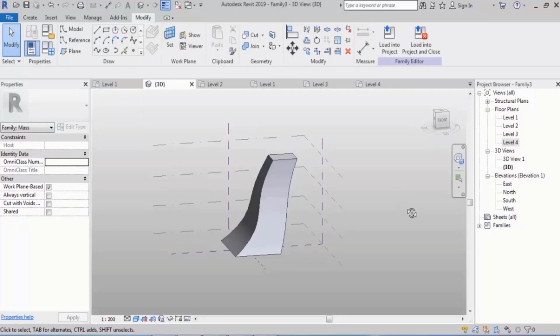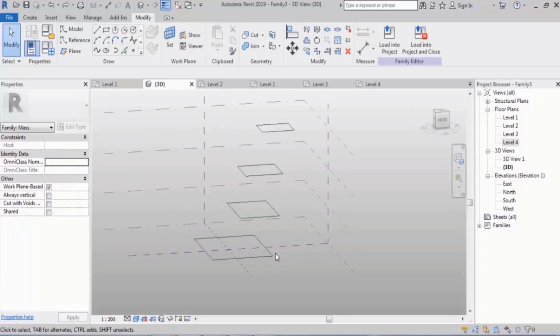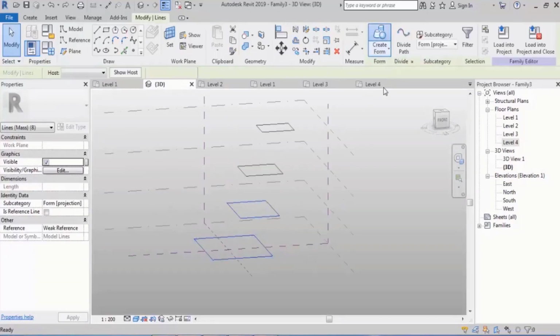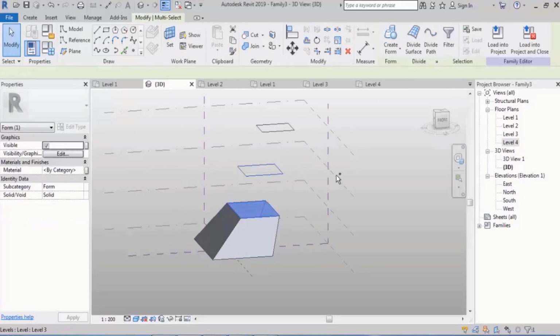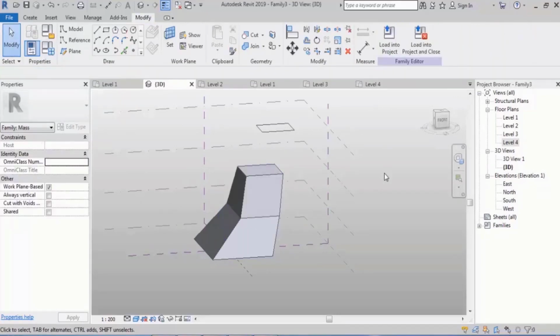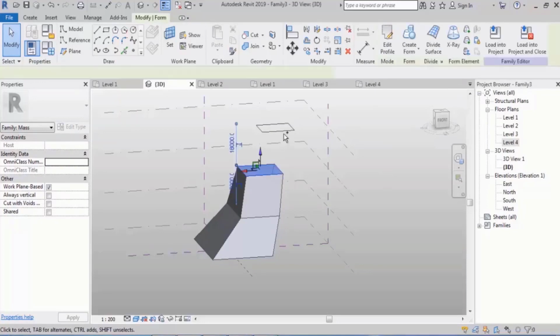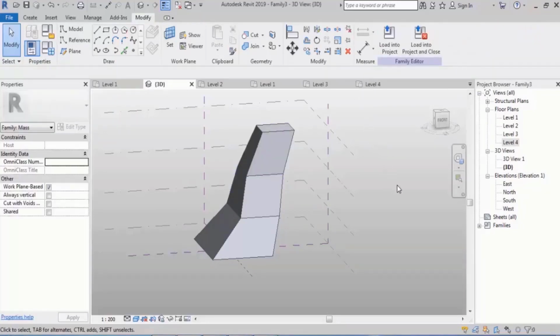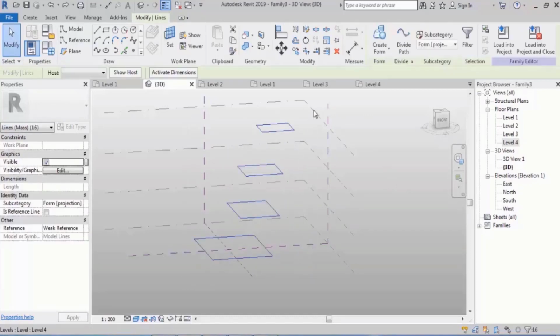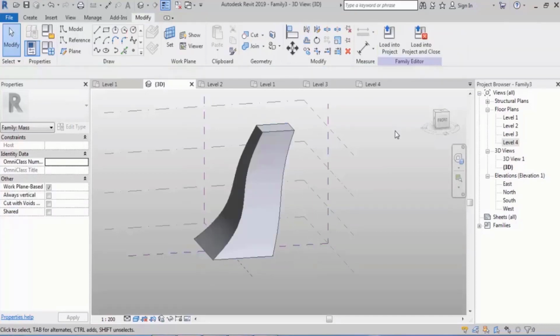In Revit, forms are connected to each other only curvedly, right? If there are two, yes, the form will be straight. But if there are more than two, they will be curved. But one of you might say that, no, I want them to be straight. Well, it will be difficult because you have to connect them 2 by 2. As you see, it's straight as long as there are 2 of them. And I don't think it's so useful. It's more logical to select them all and then create them at once together.